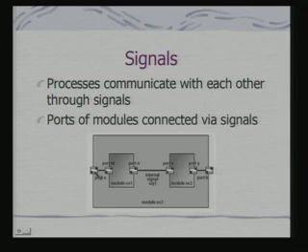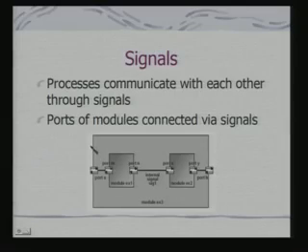And if we consider these part of a bigger module, module EX3, which consists of module EX1 and EX2, then these are the ports for communicating with the external world. So, you can see how you are actually describing really a hardware using an object oriented language. Along with it, you can even describe the software as well. So, this is the basic advantage of SystemC, right.